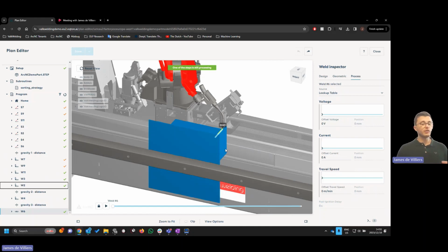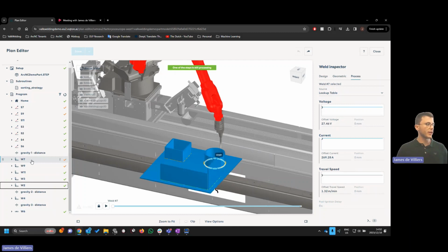So this strategy reduces manipulator movement, so how much the rotator is going to rotate during welding, and that can be adjusted over there. So now you can see, for example, if we want this weld to be last in this section, I can simply drag and drop it to the end over there. If I want this weld to be first, you can see all of these blocks are just nice blocks that we can drag around in this section to create our sequence. So very easy for you.